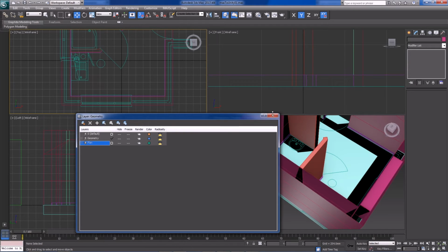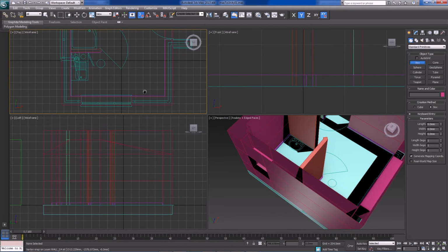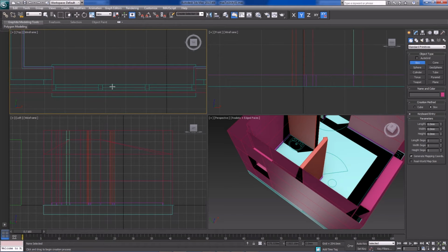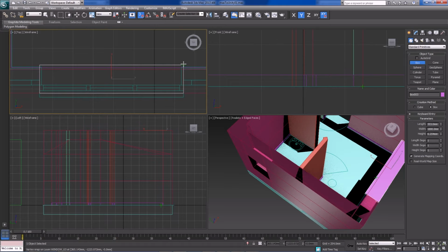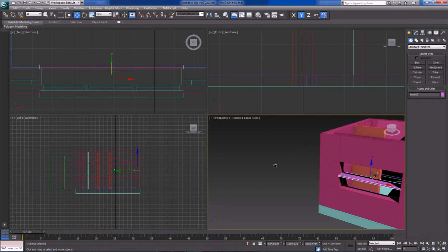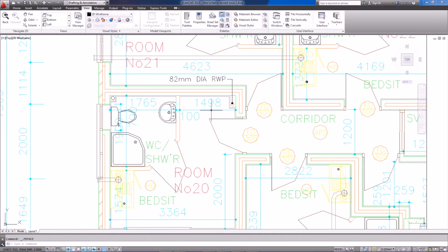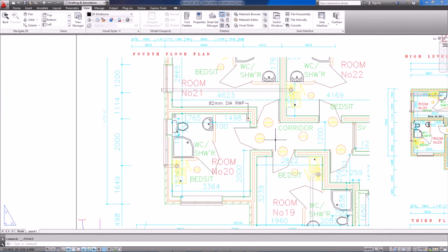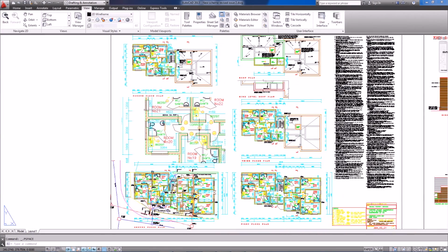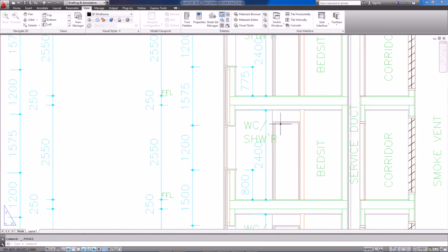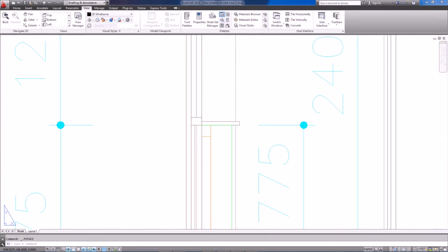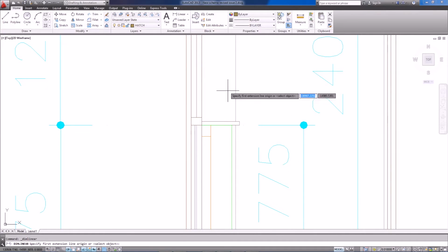So if we unhide the plans, go to create object primitives and click on the box, with snap enabled, let's just create it from here all the way to here. Now we don't have a precise thickness, but we can get that from the plans. Okay, so still in our model view here. If we just click on the model button, that will snap out of it. I've moved this a bit, but it's fine. So we should be able to see the window board here, and we do. Let's get a thickness. If we go to home linear measurement, it's 25 millimeters. So there we go.